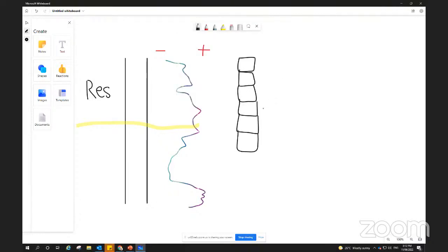So how is the upscaling process happening? Let's take Petrel for example. When you tell Petrel to run the upscale to porosity, it comes to this cell and sees the equivalent curve of porosity, and sees the maximum and the minimum value, and takes the average.